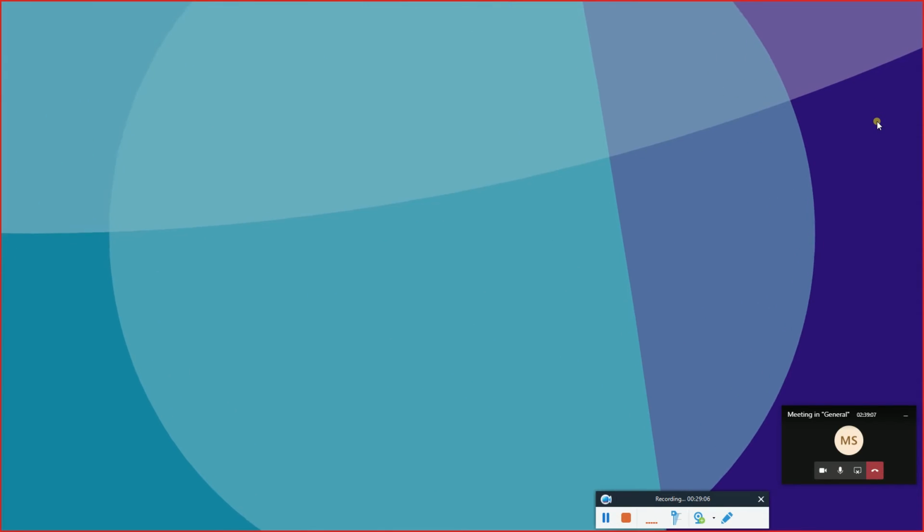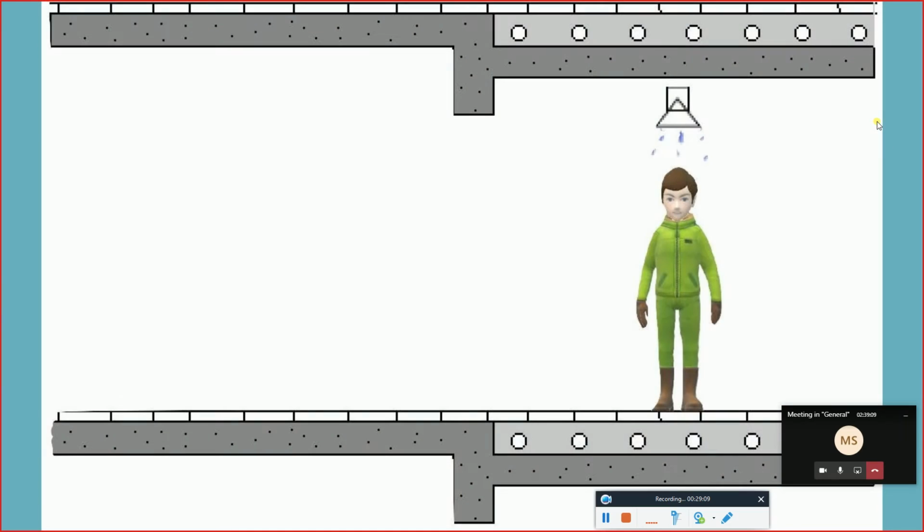Now, for the sunken slab, we use sunken slab a lot in Oman. This is an illustrated picture from your advanced RC design. Once again, a sunken slab is a slab that is made wherever there is a necessity of connection or water connection. So you can see this is a regular slab. This slab needs to be sunk down. Sunk down, meaning we lower it a little.